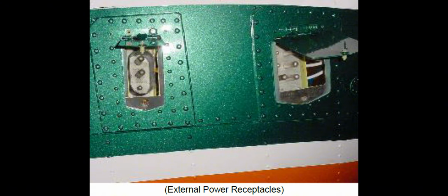If either or both generators become available to provide AC power and one or both primary bus relays become energized, DC voltage from the auxiliary contactors of one or both relays is applied to the solenoid of the AC external power control relay. The AC external power control relay energizes and the normally closed contacts open, interrupting the path to the external power relays.